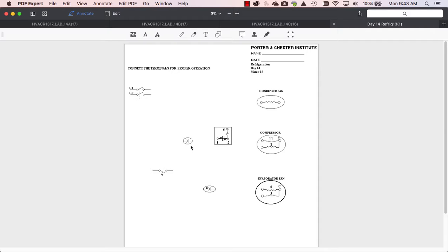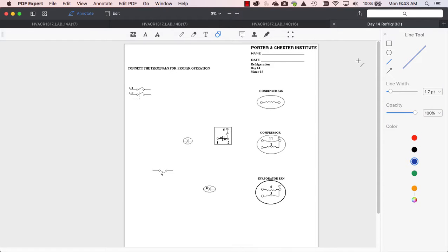On this day, we have a couple schematics we have to worry about. I'm going to go ahead and help you with the first one. This is a motor schematic. We've dealt with this one before. Pull line 1, bring it out here to be your common. Go ahead and tie in all your motors so you don't forget about that.